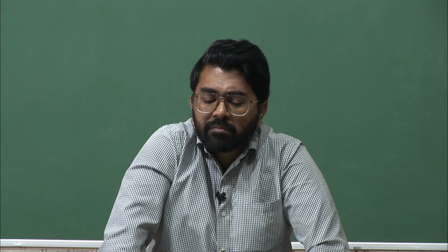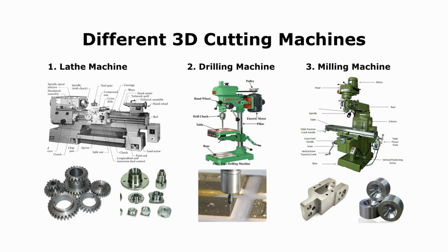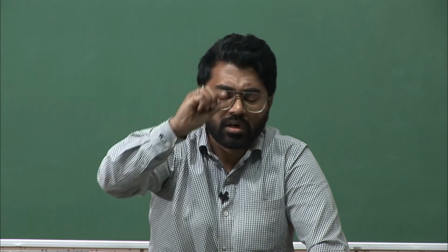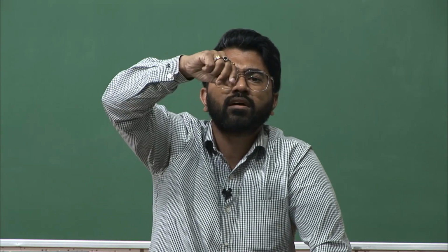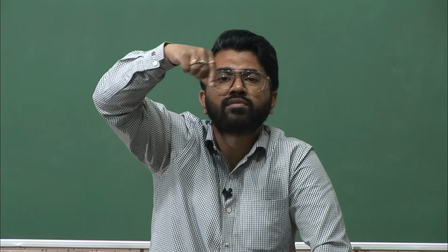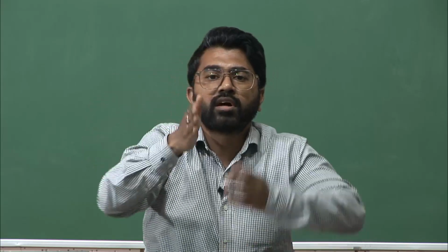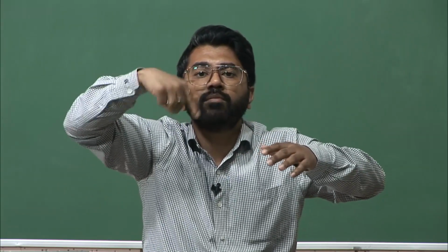Then you have a milling machine, which is a very classic machine which also has the option of drilling. But the purpose of milling is a little different. Milling has a drill chuck again, known as a spindle, and within that you have a cutter which is very similar to a drill, but it is a cutting tool. A drill has a pitch and design specifically built for making a hole, but a cutter has cutting or sharp edges which can cut material out.